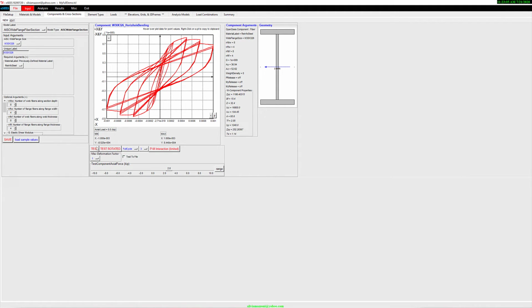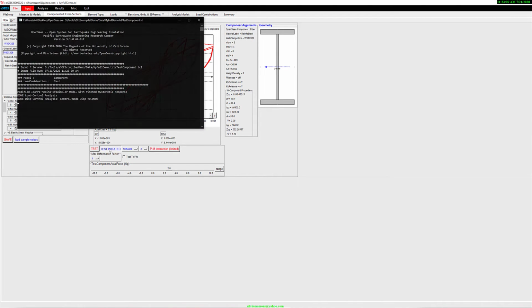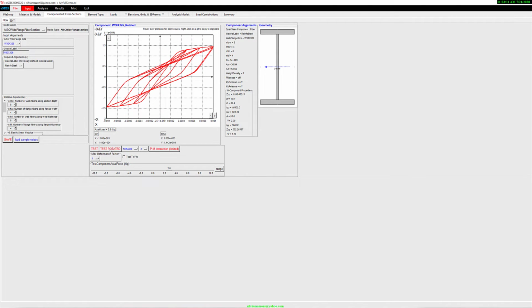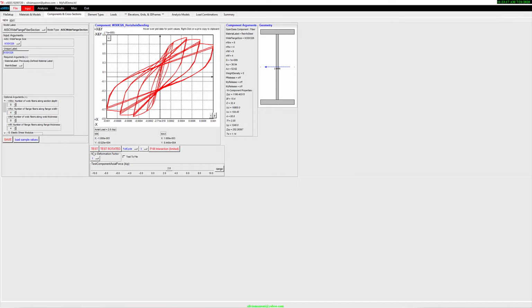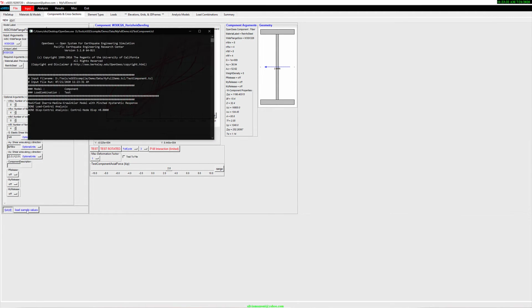And you can also test it. This is about this axis, but you can test it in the rotated direction, and that's the moment curvature in that direction. So let's go back and test this section. It looks really good. We can change axial forces if you want. You can play with the number of fibers and different properties, but I'm going to just say in these options right now, just let them be. If you want, play with them and see what it really means. So I'm going to save this cross section.